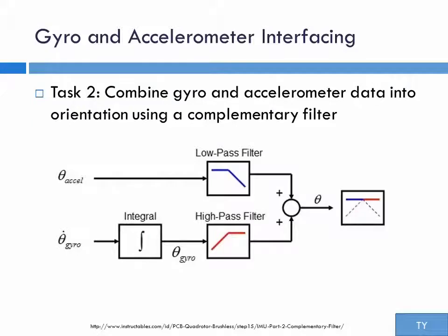The complementary filter combines the high-pass gyroscope measurement and the low-pass accelerometer measurement and outputs orientation data in degrees for x, y, and z axes, which will be used as inputs for the wireframe cube. Gyro measures angular velocity in degrees per second. Integration is constantly performed at each sample point in order to obtain the degree value.